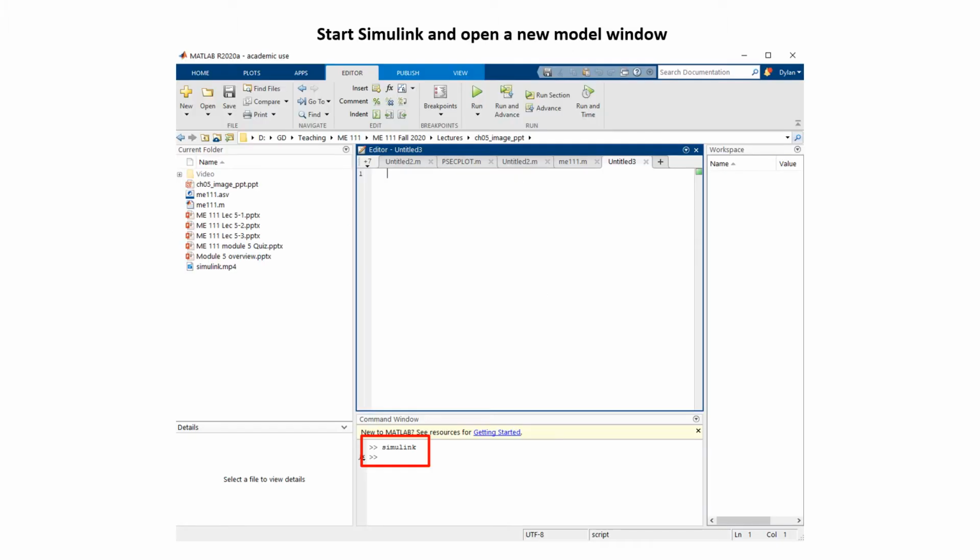So we're going to start from the very beginning here. How do we solve this problem using Simulink within MATLAB? Well, the first question is, how do we get Simulink opened within MATLAB? What we first want to do is start a new MATLAB window, pop open MATLAB, and run it. I'm just using release 2020a from the university, so you should be able to download that. If you haven't downloaded that yet, I will put up some links to the UVM site in order to download MATLAB. We want to make sure that we do have the Simulink add-on within it as well.